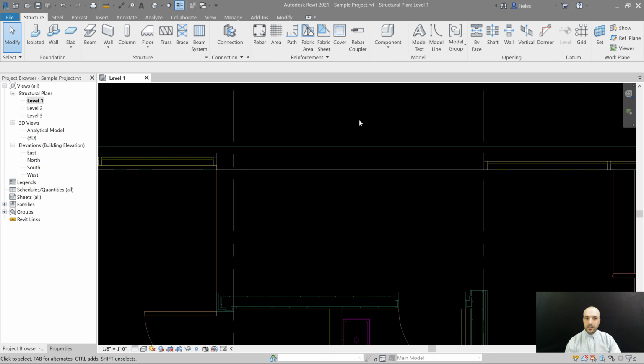I'm going to model another wall out here. So I'm going to select that original one. For create similar, I'll type in CS this time. And I'll show you another way of modeling this wall by using the pick lines option. Our properties stayed the same on our options bar. And now I can use an existing line that already exists to place my wall. So in this case, I will select this outside version, right?